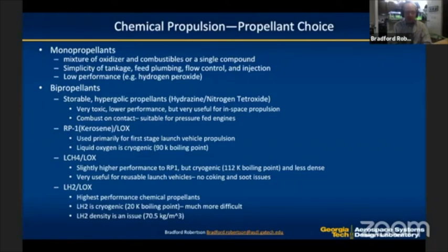If you see the Space Shuttle or now SLS that uses hydrogen systems, the vast majority of the size of that launch vehicle is the hydrogen. That's 70 kilograms per cubic meter. And that's generally an issue because now I have to have much larger tankage. If I want to keep that cool in space, I have to have even more insulation, or if I have an active cryocooler system, that's even more area that I need to cover.